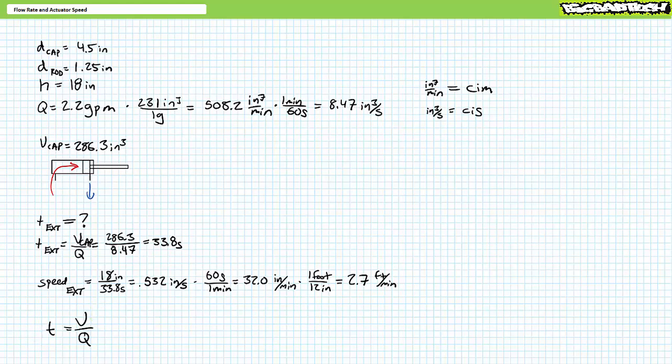It all makes sense. Case in point, consider the act of retraction for this same double-acting cylinder. The act of retraction necessitates the smaller tube-like volume of the rod end be filled, while simultaneously the volume of the cap end is exhausted at low pressure. During the act of retraction, a solid steel rod is pulled into the rod end, which occupies space, thus displacing oil entering the rod end. Long story short, the tubular rod end volume necessitates less oil volume be filled than the fully cylindrical cap end.